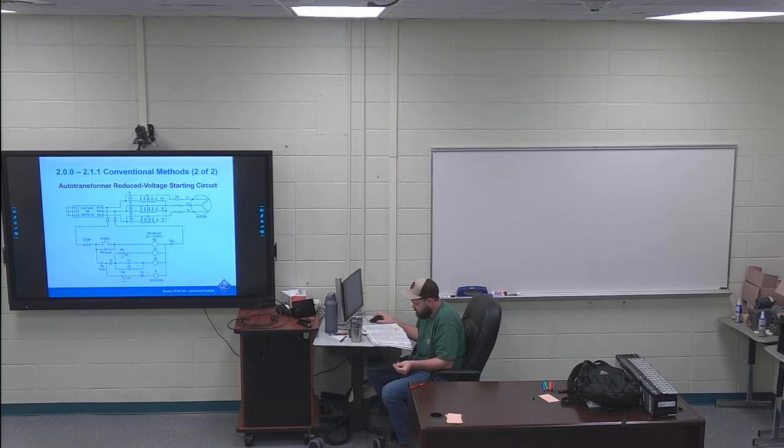As long as the motor is running in the full voltage condition, timing relay TR and contactor R remain energized. Only an overload or pressing the stop push button stops the motor and resets the circuit. So pretty much need to read through those 3 paragraphs and see how this circuit operates.